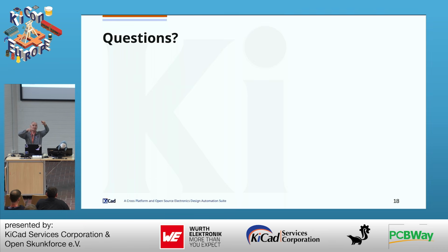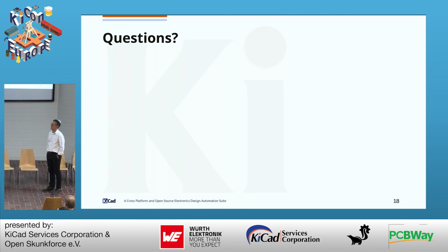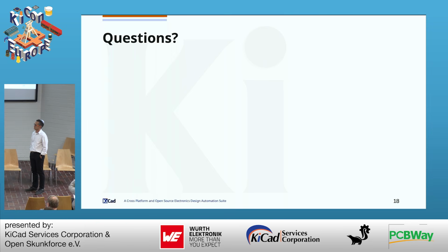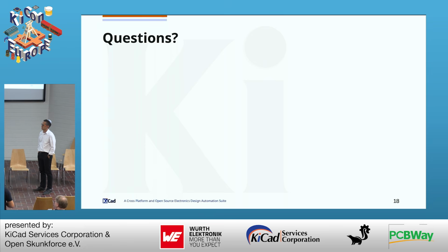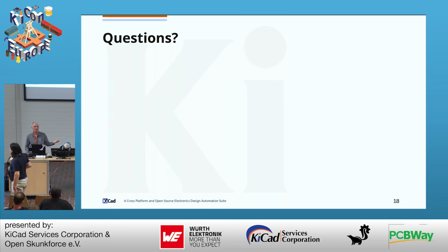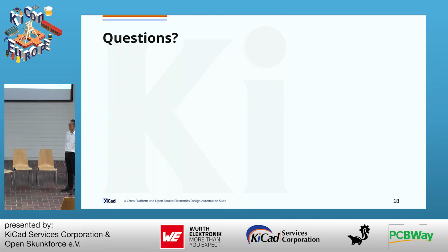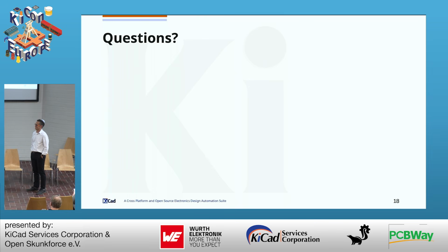Now, maybe you have a 1K with this part number and a 1K with that part number. That's a diff, right? Otherwise we'd have to store the same information every time, and you would have all this variant information in the board file that wouldn't be necessary to generate the exact same output. It'll be transparent. You can select all 4 and change it. You won't notice the difference. Internally, it'll just be the new part for every variant.